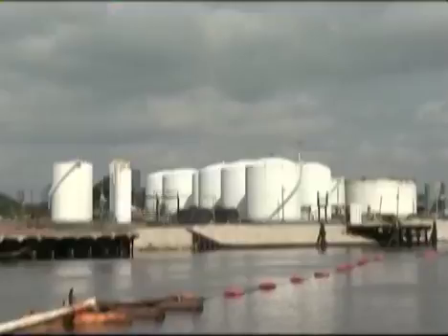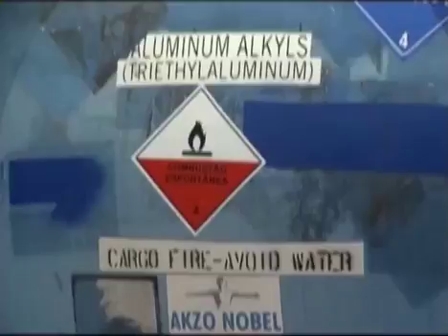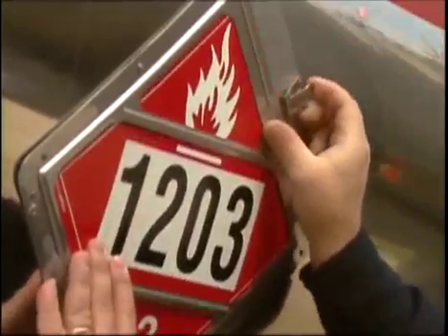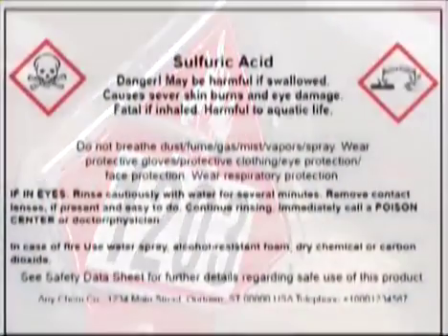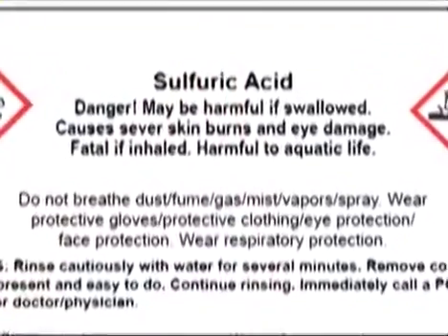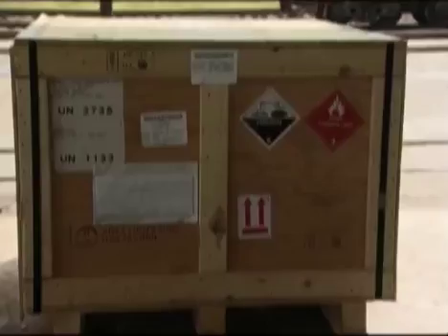Chemical manufacturers, importers, and distributors are responsible for labeling, tagging, or marking each container, commonly known as the primary container, of classified hazardous chemicals they ship. OSHA requires the information be prominently displayed in English on each container. OSHA also requires the name, address, and telephone number of the manufacturer, importer, or other responsible party be displayed on the shipped container.